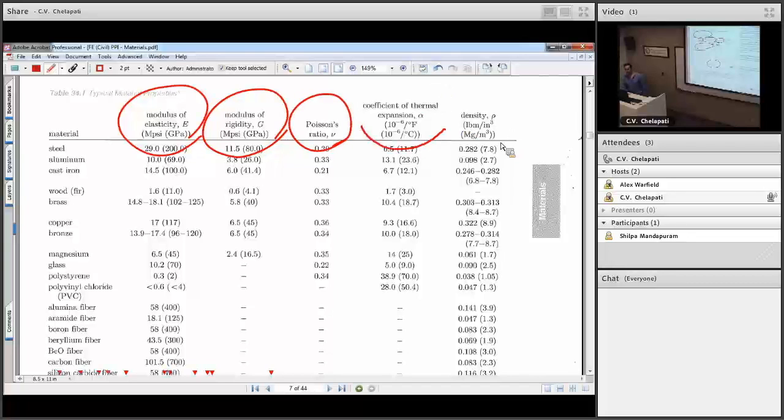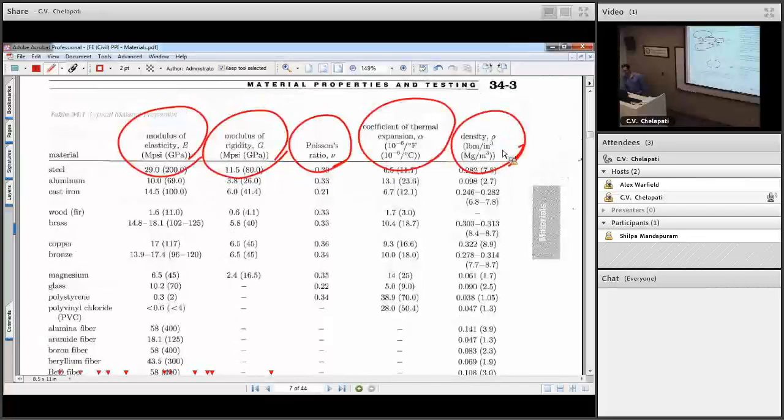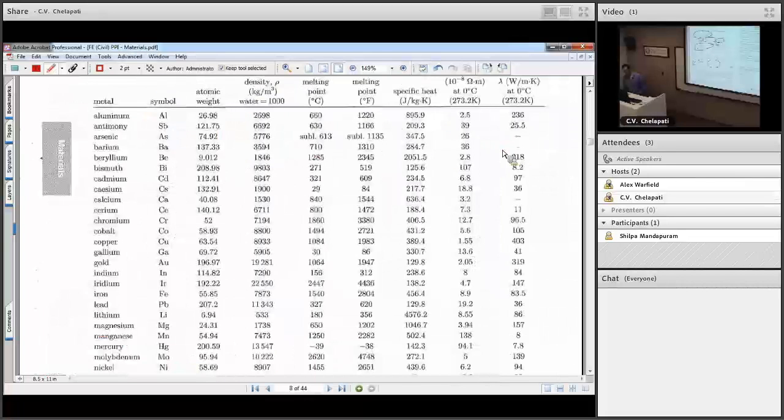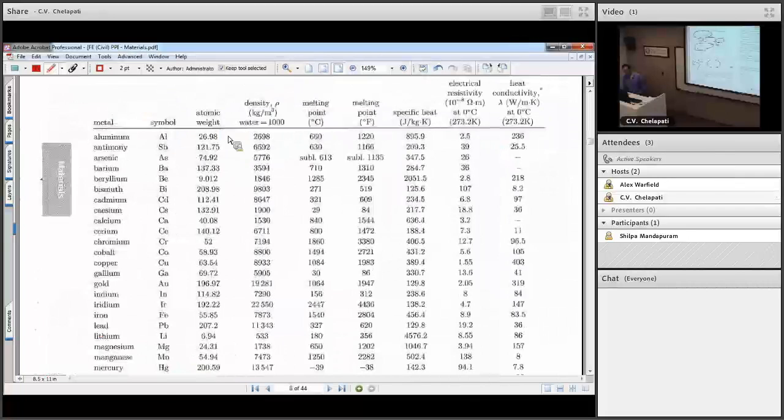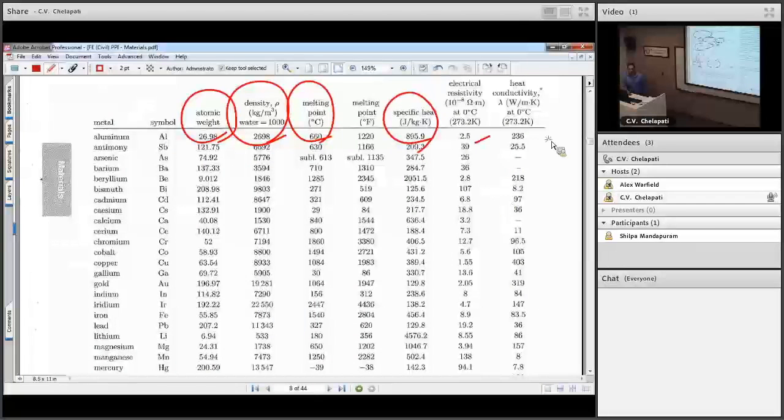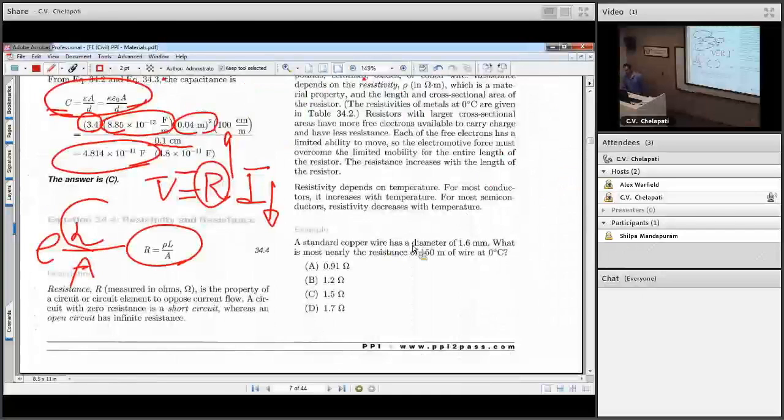Resistance in material is an important factor to consider for electrical conductivity. So it's the resistivity rho multiplied by the length divided by A. By the length, basically if the material has a higher length, the resistance of the material to electric current will increase, and we know that V, the voltage, is equal to R, the resistance, multiplied by I, the current. So as the length increases, the resistance increases. For the same voltage, you get a lower current passing through the material.